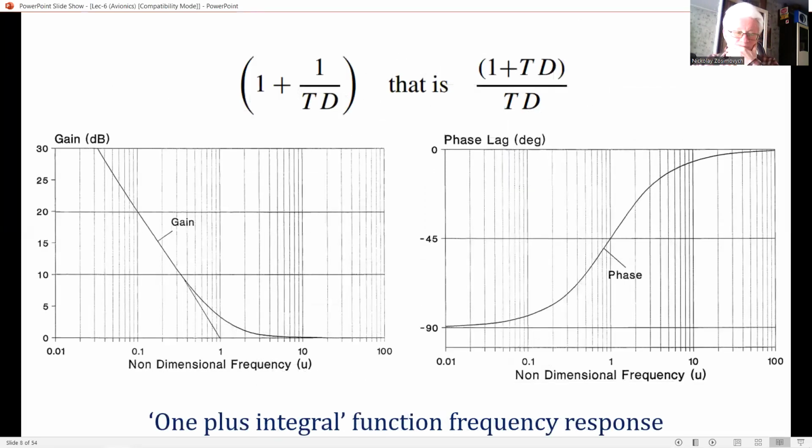And this figure illustrates the gain and phase versus the frequency characteristics for proportional plus integral control. The transfer function, let's look at this second expression on the top. It can be seen that the gain approaches unity at high frequency and should be equal to 0 decibel with 0